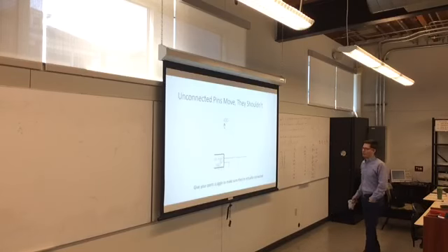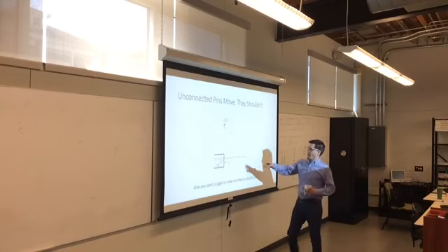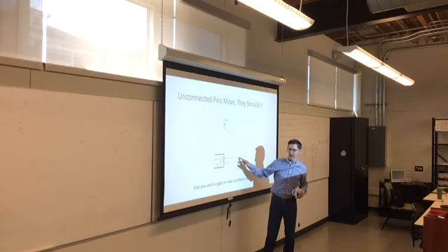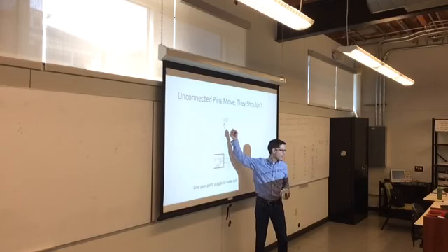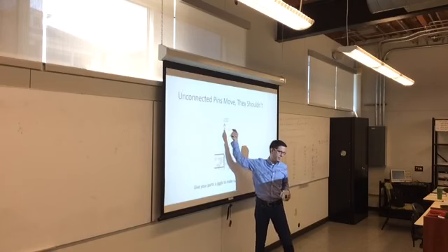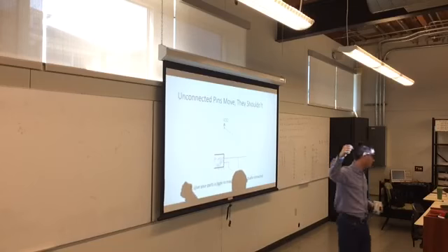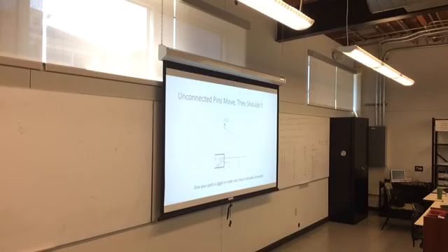So here's an example of this. That was my diagram for here, and it said that I had a misconnected net here. I thought I was connecting the output of my power supply to VCC. But when I take the VCC symbol and pull it away, my net should stretch and follow me, but it actually ripped the net away because it wasn't actually connected.